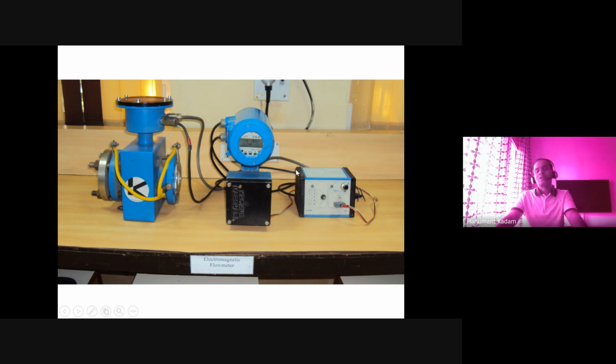Suppose your range is 0 to 100 liters per hour, for example. So 0 liters per hour is 0, and span is 100 liters per hour. Here you have a knob. Through that you can create a signal for 0 and feed it to the transmitter electronics. That time the transmitter should show 0, right? There are some buttons also here. Through that it is also possible, but that procedure needs practice and the manual. Some push buttons, pressed one, two, three times like this, and through that you can calibrate. But nowadays these simulators are available, and the only thing is these simulators are very costly.